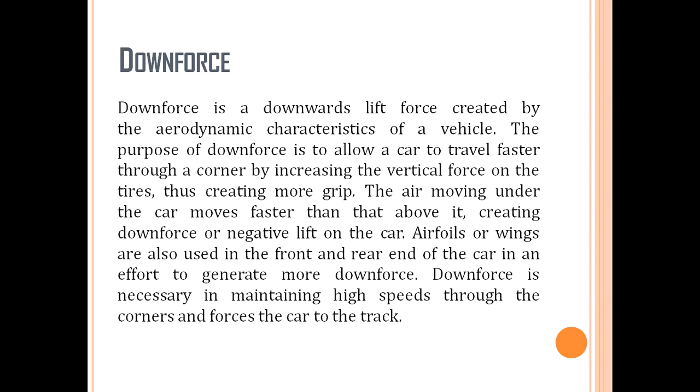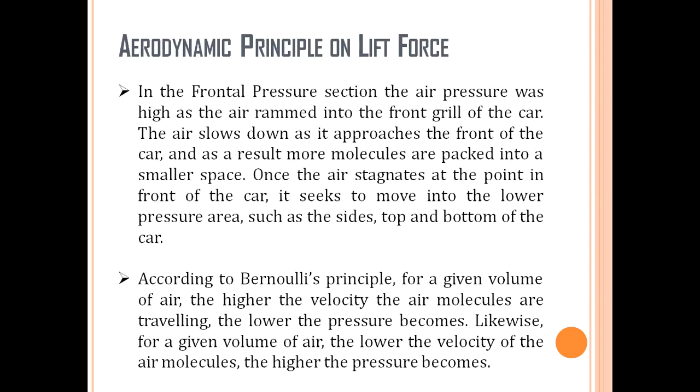Airfoils or wings are also sometimes used at the front and rear end of the vehicle to generate more downforce. Okay, downforce is necessary in maintaining the high speeds through the corners and forces the car to track with the road. Okay. Now coming to the aerodynamic principle on lift force.